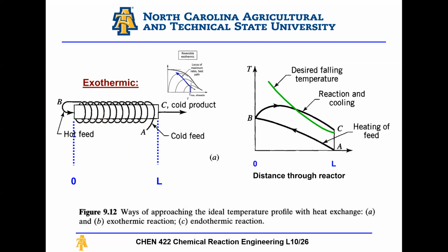And if I control the flow rate effectively enough, this allows me to have a temperature gradient along the reactor length, right? Because this feed is entering at a high temperature, I'm having an exothermic reaction here, but this exothermic reaction is being cooled by the fresh cooled feed incoming in this cooling coil, and eventually my products are cooled. So the temperature along the length of the reactor is dropping, okay?